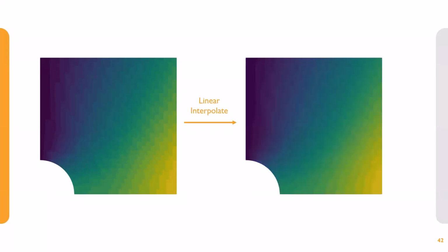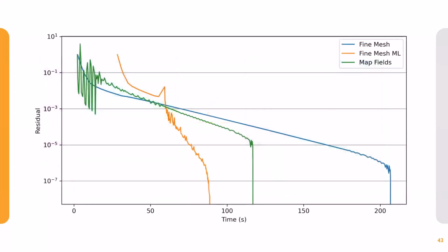So you might say, well, Scott, we already have the coarse mesh solution. Why don't we just interpolate this to the fine mesh and let it converge normally? So it's a good idea. So I've compared it to this, which the green slope is. So this is kind of, I think, what multigrid is based on, but I haven't delved into the world of multigrid too much yet. But this is just a simple comparison. So even with this, it's still at around a 34% speed up.